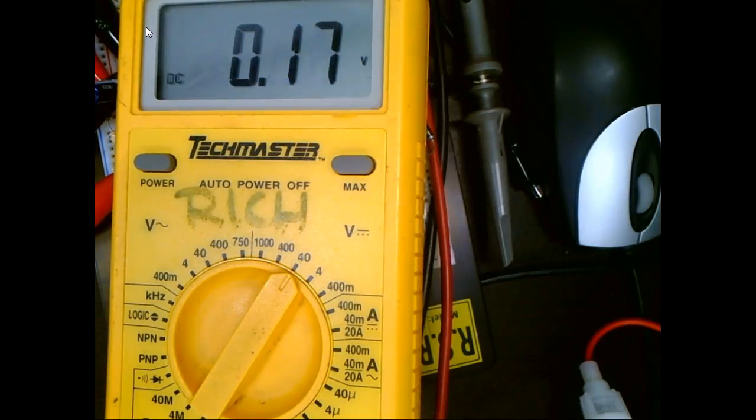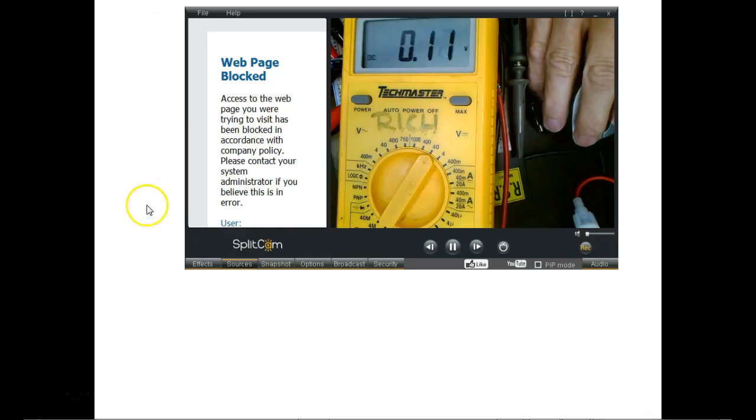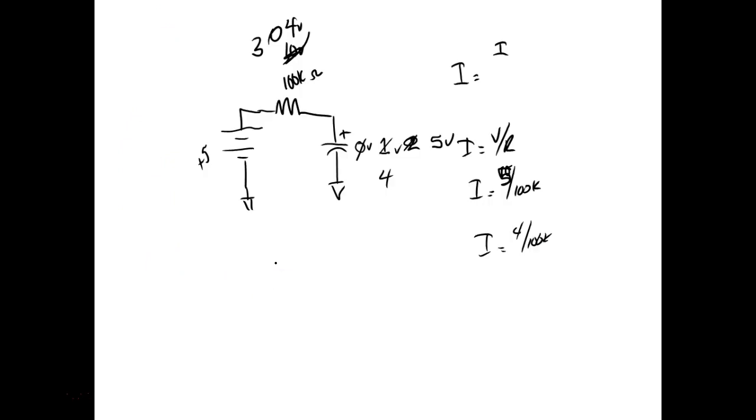They're not real hard. Anybody that's had AC has probably heard of RC time constants. But we don't need to use 5 times RC, because we're never going to fully charge it. It only charges once, on the peak, and after that it discharges, and it never tries to discharge completely. So we'll just use R times C, because we're never going to discharge it below 63%.